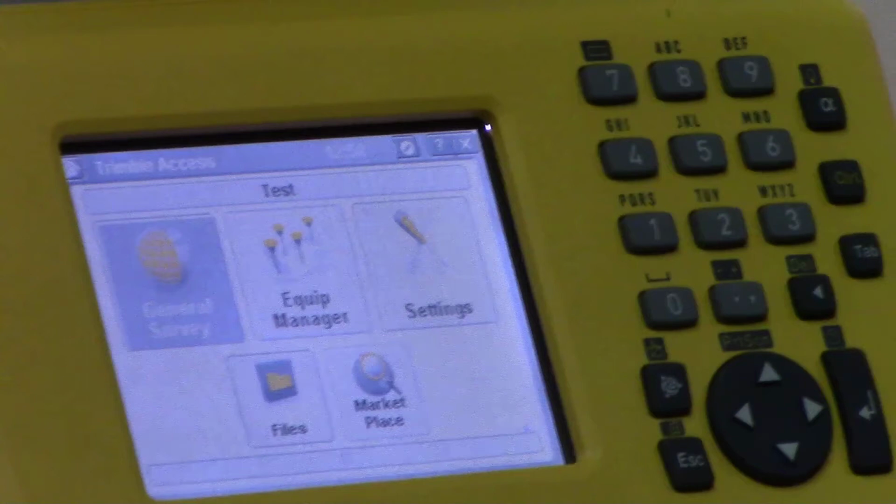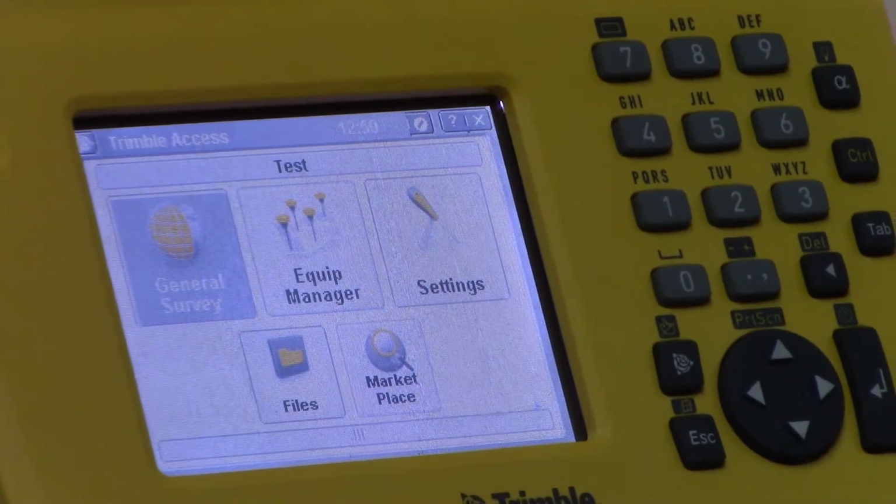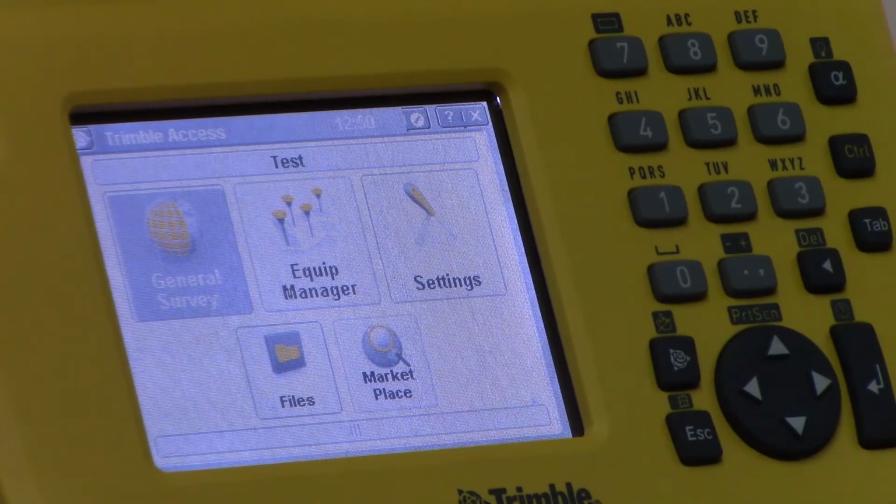And we would like now to start manipulating the resection on the station directly. Let's go to the lab. Okay, we would like to start today a new experiment, which is resection. Resection, it's another way to set up your total station.